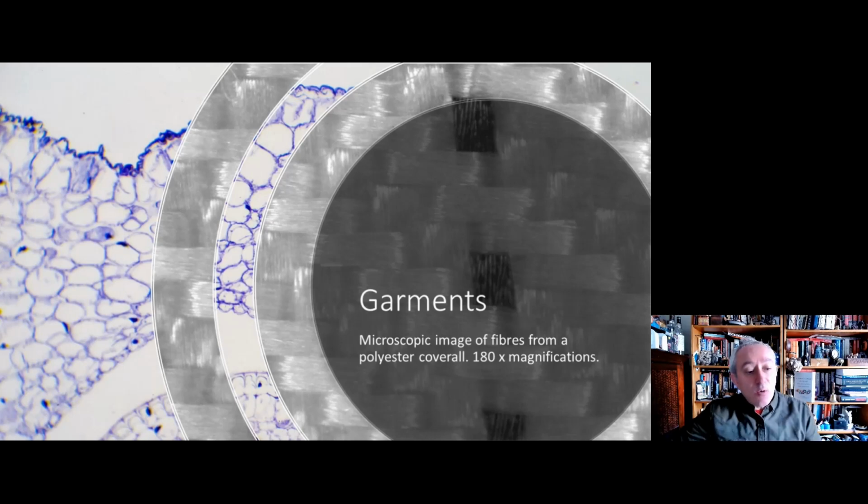Now, I mentioned also about garments being filters. Well, here is a 120 times magnification of clean room garment, and it looks like a patchwork quilt, but it's actually over layers of the appropriate non-fibrous, non-particle releasing polyester type materials, and it's acting there as a filter to keep contamination in. And that's quite a good photo. If you can't start thinking my gown is a filter, well, here's an illustration that helps to guide that in the right direction.